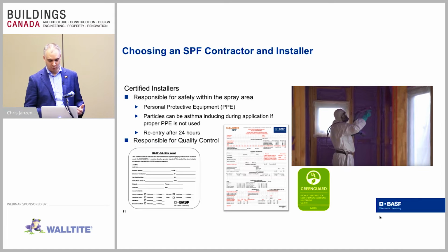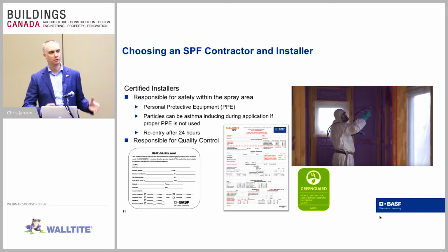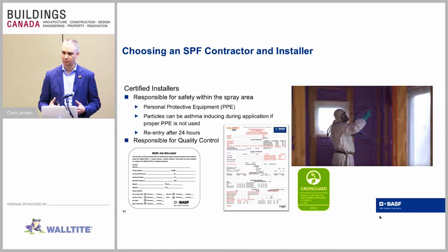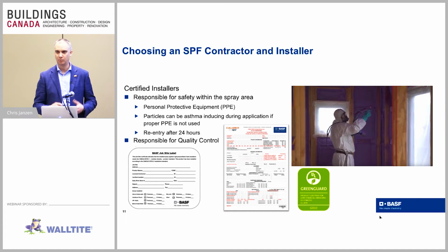And the reason why some of that's important, some of the responsibilities of the certified installer on site, is one of the biggest things, other than just putting the foam in there, is they're responsible for people's safety within that spray foam area. So you can see the guy spraying foam, he's got his Tyvek coveralls on, he's all suited up, spraying foam, lots of PPE, fresh air, and all that kind of stuff. So he's protected. The reason why they're protected in the spray area is because they're atomizing the isocyanate and resin. It's reacting as it goes through the air to polyurethane foam and reacting on the wall. And typically, with proper ventilation rates, the risk of inhaling these particles is gone after about an hour.